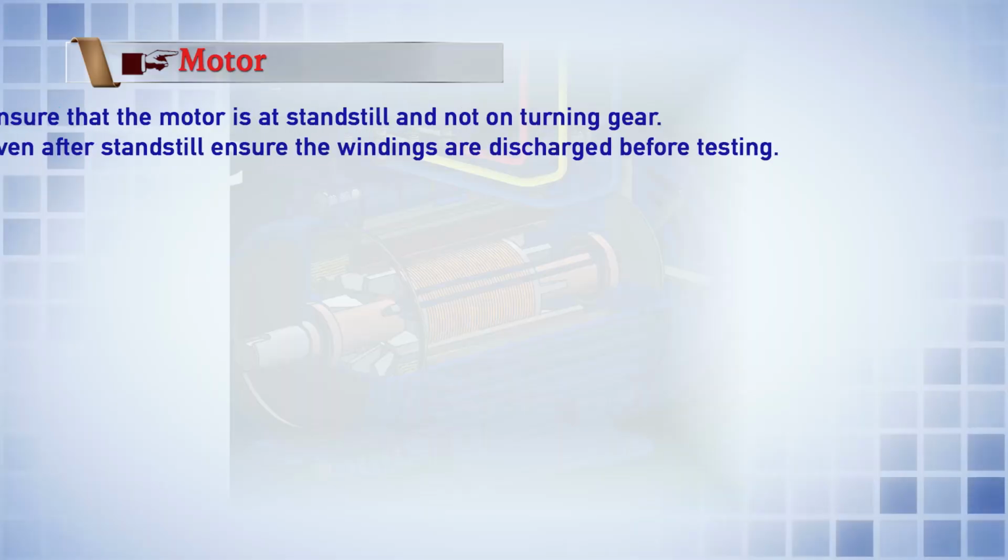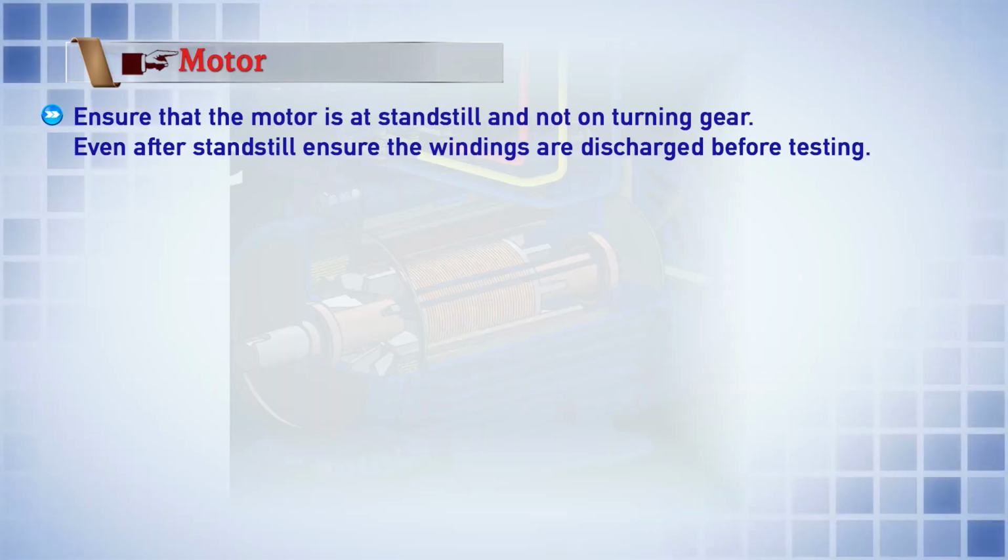So all these are single-phase induction motors. While testing a motor, the following safety precautions must be followed. First point is to ensure that the motor is at standstill and not on turning gear. Even after standstill, ensure the windings are discharged before testing.